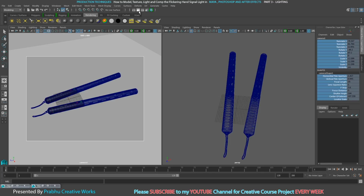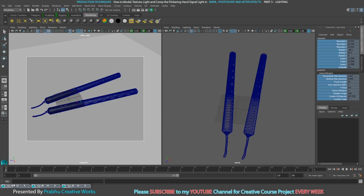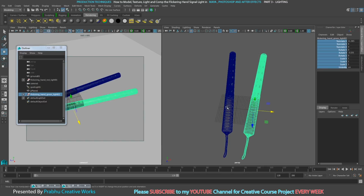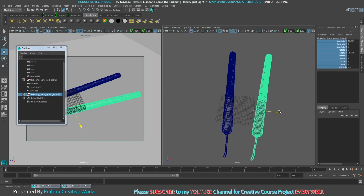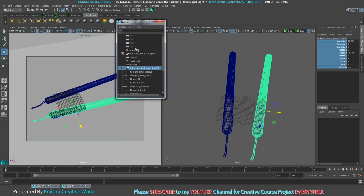So then click render. Okay, I forgot to change the color here. This one is the green light, this one is the red light. So I will go to the outliner, select my green light group, press W and move it further this way. Now I go inside my green light group and select my point light.